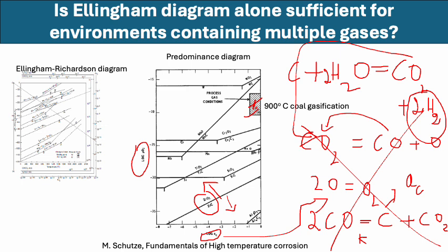So in this condition, if you take niobium, that may be present as an alloying element in the alloy, this is in the stability region of niobium carbide. So niobium carbides will start to form. But if you take chromium, we are in the chromium oxide stability region. So we will form Cr2O3 and niobium carbide and tungsten carbide. All others, the titanium will also be predominantly as oxide. Predominantly is a wrong word. The equilibrium phase is titanium oxide, not titanium carbide.